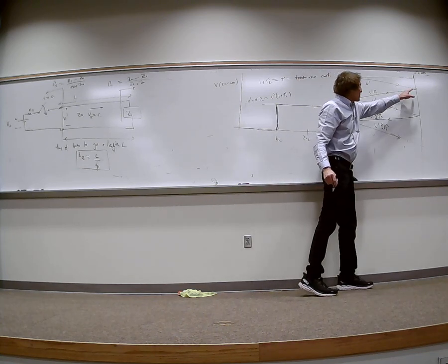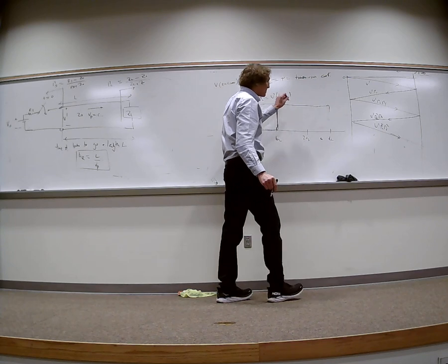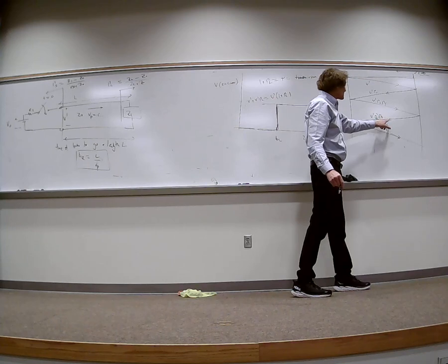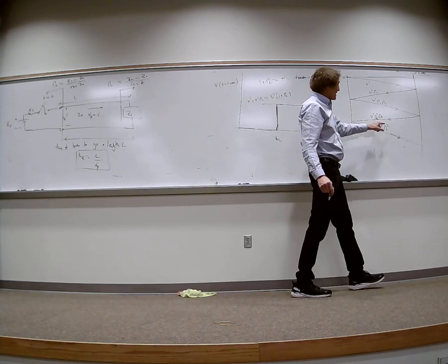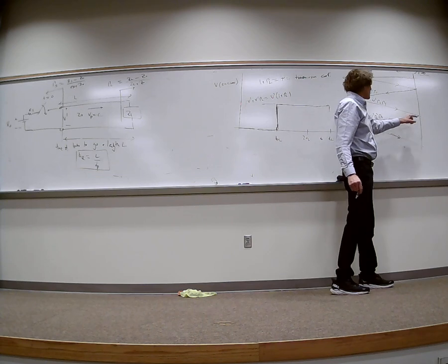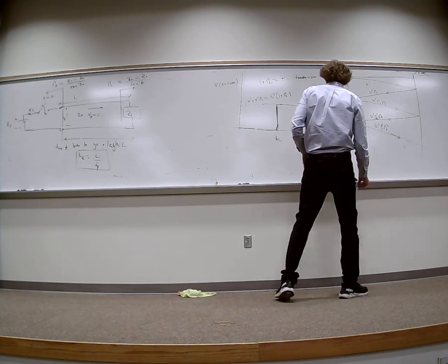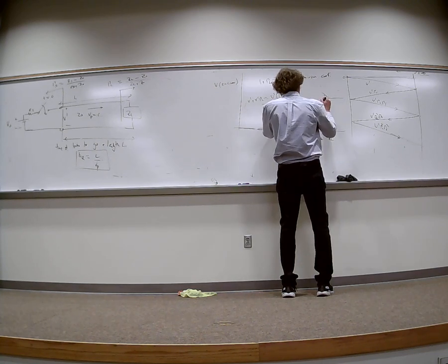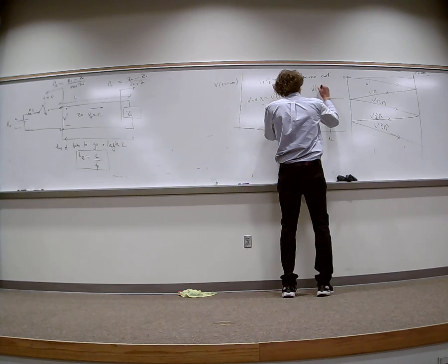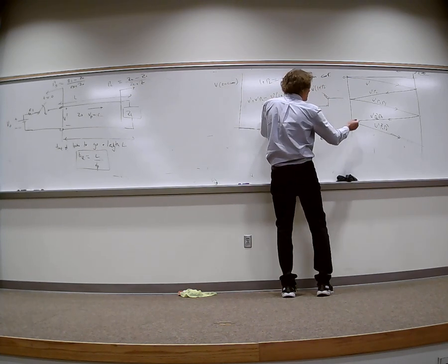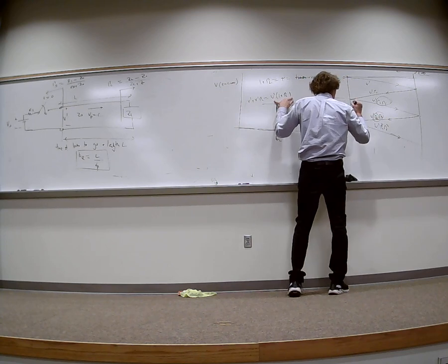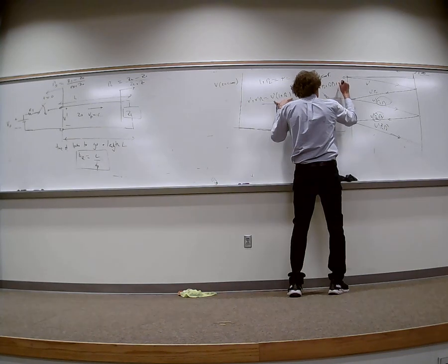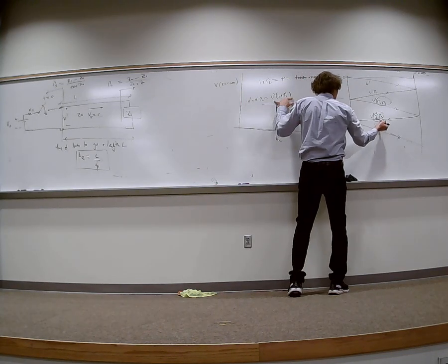Okay. So you had this value, right? Now what are you going to add to it? It comes down. Hits, this one's coming this way, this one's coming this way. You all follow me? So now when you superimpose them at that point, you're going to add this and this to what was before. So now it's going to change, and I don't know if it's going up or down. I'm going to have it go up. And now what's here is going to be V prime times 1 plus gamma L, right? But it's also going to be this and this added to it. So it's going to be plus gamma L gamma S, plus gamma L squared times gamma S.